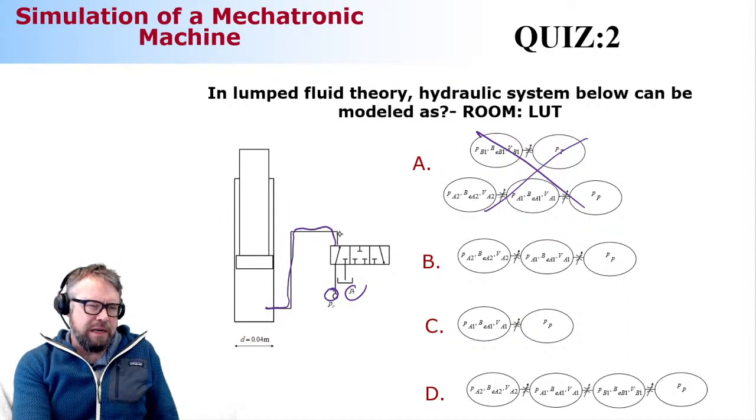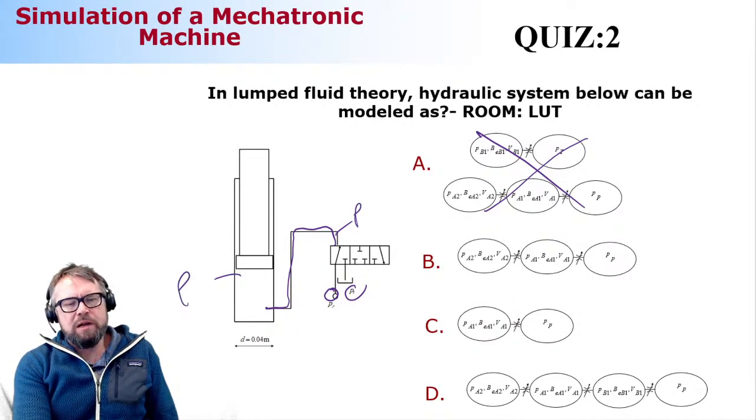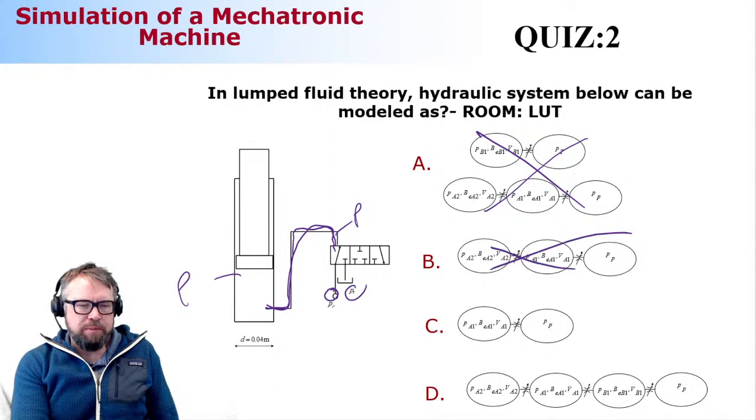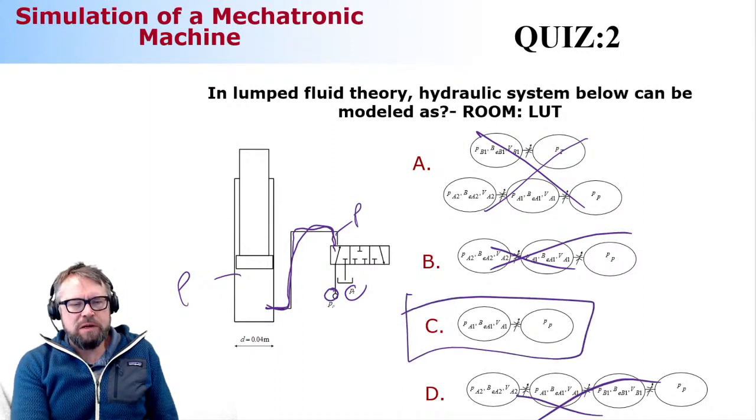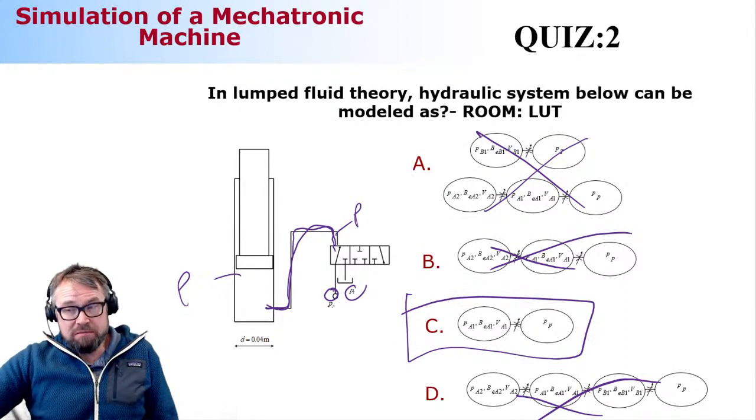And in similar cases like this previous slide, we can assume that the pressure here and here are having the same numerical values. So basically you need just the one volume to compute the pressure here. One, not two. So that's why this is off the picture. Definitely you don't need three. So the only one left is this one because you need to have just the one pressure to compute it. That's it. So just one differential equation will do it.